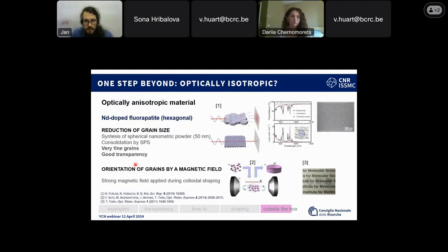With the second powder, it's not so easy. Agglomerates are hard with irregular shape, and we can see that milling is not so efficient. So compared to the first case, probably we will have lower density of green bodies with more defects.